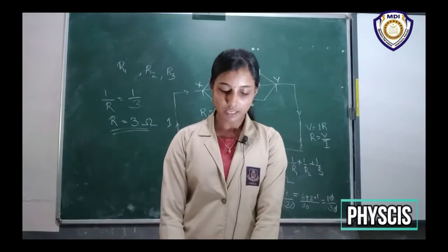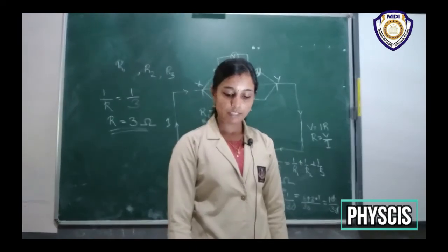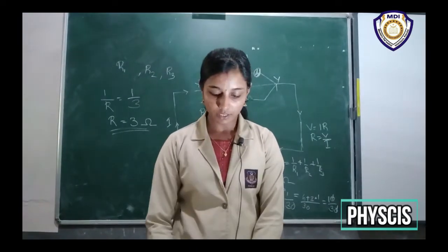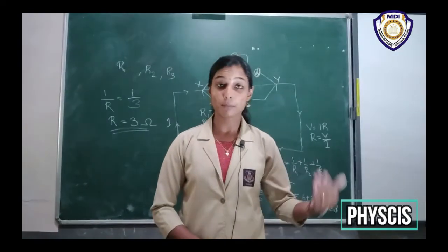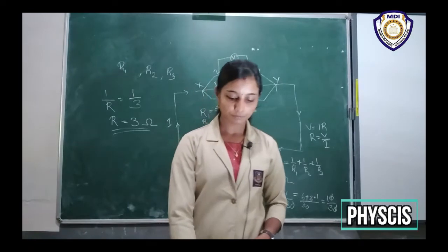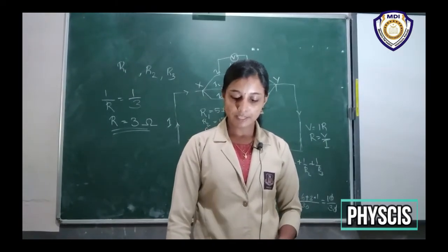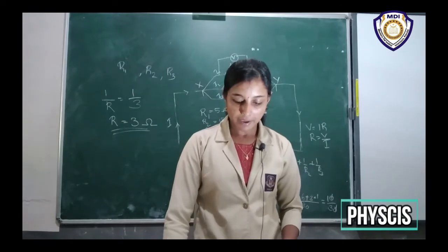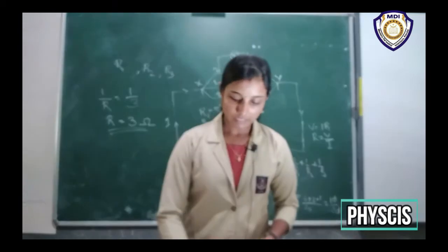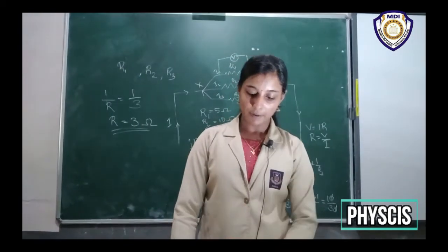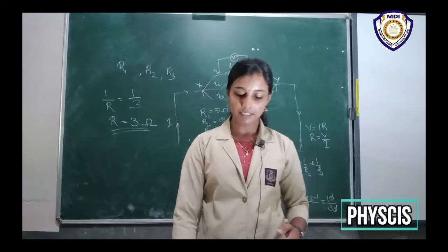Another major disadvantage of a series circuit is that if one component fails, the circuit is broken and none of the components work. We discussed all this in the previous class. If you have seen fairy lights used to decorate a building on festivals or marriage celebrations, you might have seen an electrician spending a lot of time locating and replacing the dead bulb.